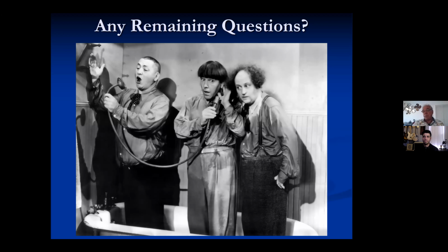So you just have to hook up an active, something unity gain. That's all you want is unity gain. I'll even take a couple of dB loss if I have to. And I have. Is it possible to have RF saturation in an in-ear pack if an artist is too close to a transmit antenna? Yeah, sure. This is great. This is a good question.